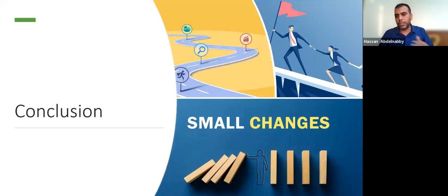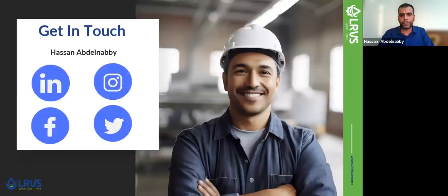And believe me, any small change can create a huge difference. So if you enter the plant and you convince them to switch from a manual greasing gun to pneumatic greasers that have a dedicated type of grease, this is a huge win. If you convince them to perform oil analysis every 3 months, every 6 months, any small change can create a huge impact at the end of the day.